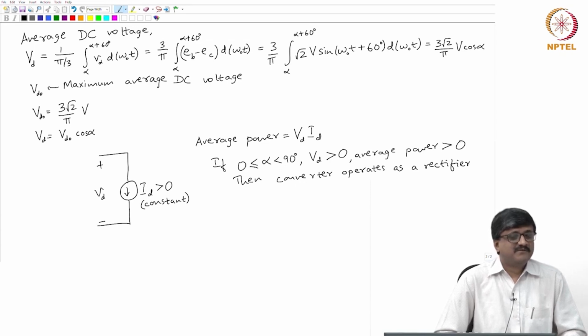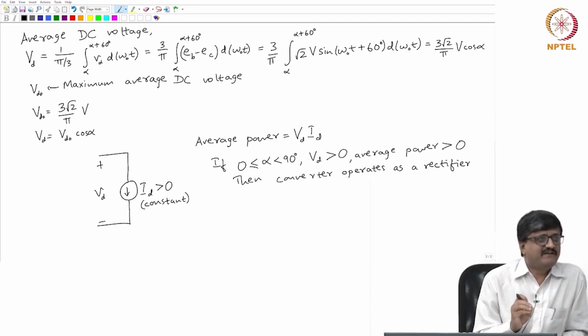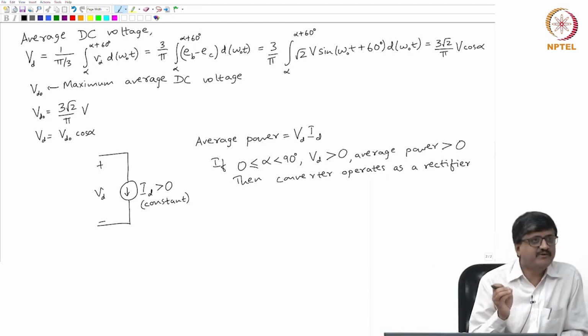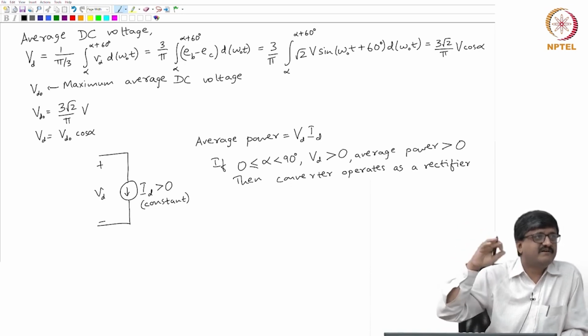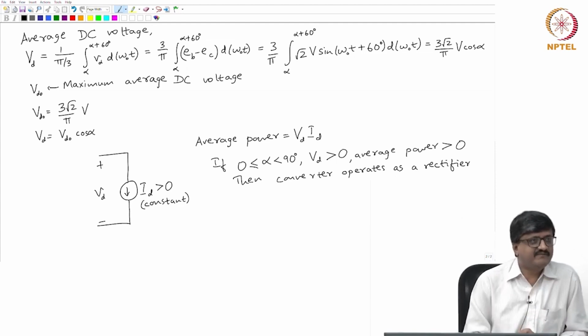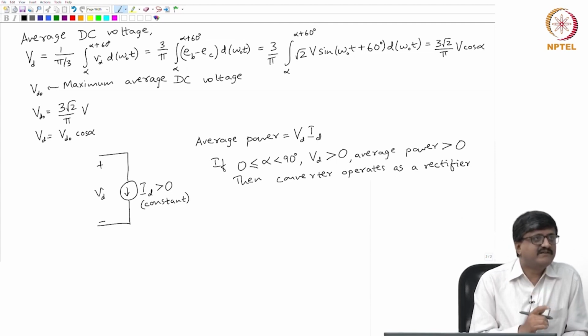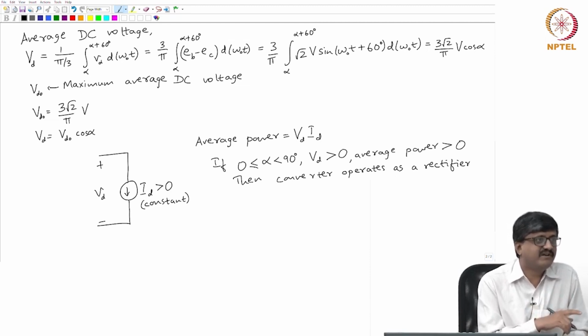Yeah. So, finally, it is some frequency which is appearing and which should not be there. Say on the DC side we want only DC quantity, but there are other periodic waveforms appearing on the DC side in the case of voltage. On the AC side as well we want only fundamental, but we do not have DC on the AC side, but we have some other harmonic components.